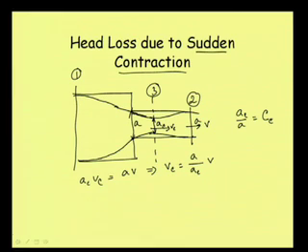So Cc is AC by A, and that is why we can write this as V by Cc. Well, this is what we can have. And then of course, we have standard values for this Cc. We have some value for Cc for different ratios of, say, this area and this area. Say if we give this as A2 by A1, then in proportion to this ratio we can have some value for Cc, and as such this can be used for calculating the value.